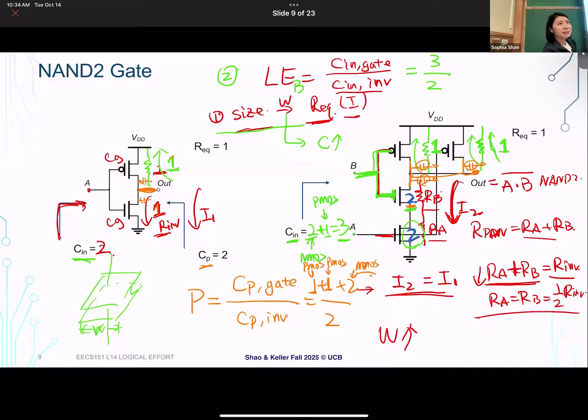When we talk about the drain capacitance, does it matter which part of the circuit it's on? That's a good question. When you think about things that need to be charged and discharged, right? For all the drain capacitance, one side is ground, the other side is the output, right? But whenever the output switches, the capacitor needs to be charged and discharged, right? So in that case, it doesn't even matter whether the circuit is on or off. Those are directly connected to the output node, right? It's connected to the drain node, right? So it doesn't really matter whether the circuit is on or off.